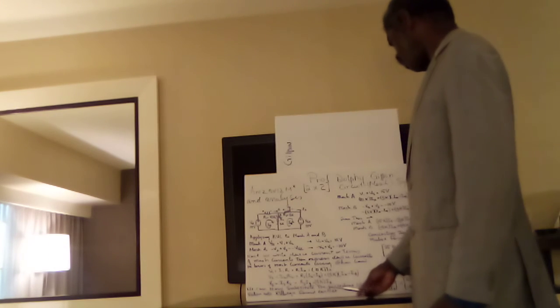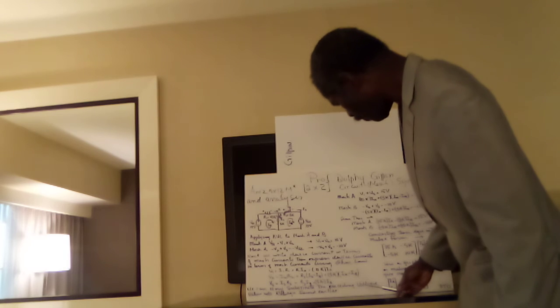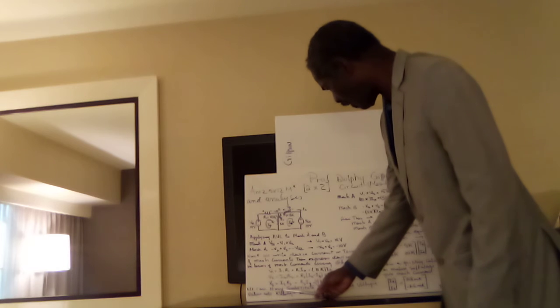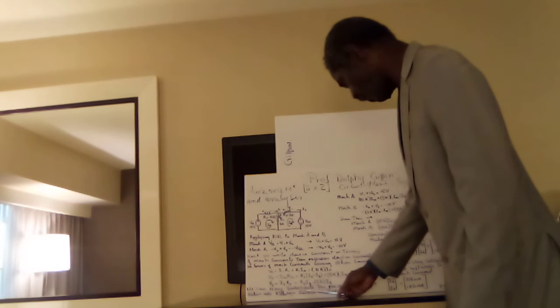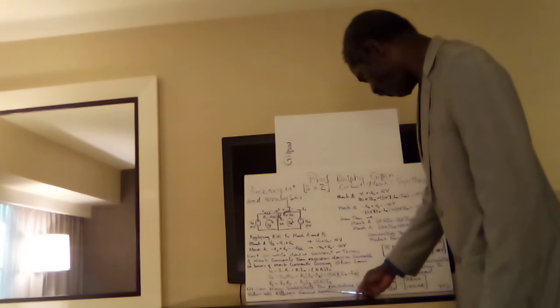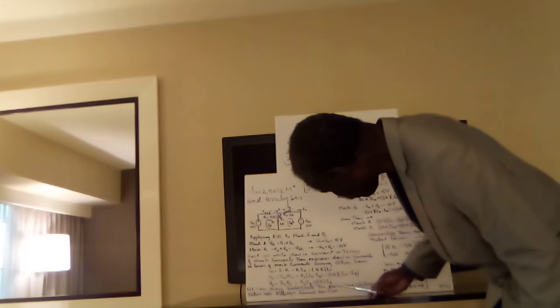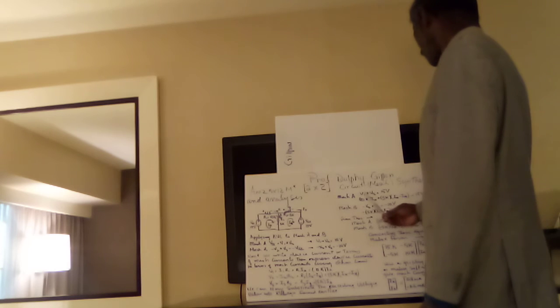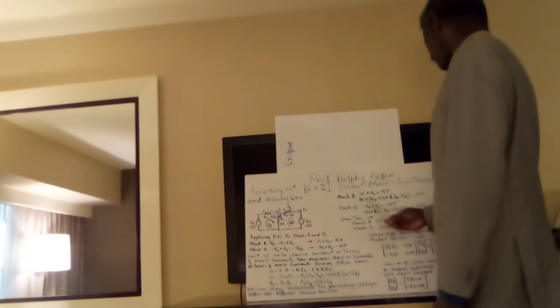So now we can substitute the preceding voltages into the Kirchhoff voltage law that we found earlier. Now mesh A: V1 plus V2 equals 15 volts, so 10 kilo ohms times IA plus 5 kilo ohms times IA minus IB equals 15 volts.